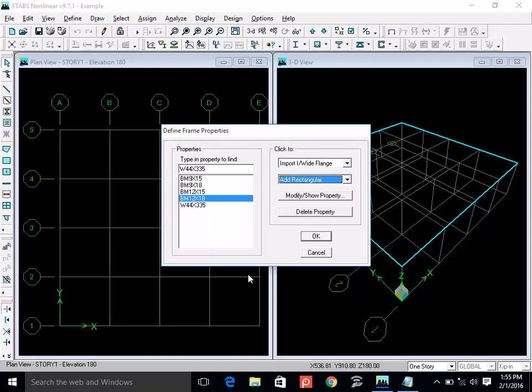But it's not the case that you always have square columns. You can also have rectangular columns. Even in rectangular column, you move in the size of 3 inch. Say 12 inch by 15 inches, 15 inch by 18 inches, or 18 inches by 21 inches, sometimes 15 inches by 21 inches. There is no universal rule, but you will learn this thing when you will practically design structures.